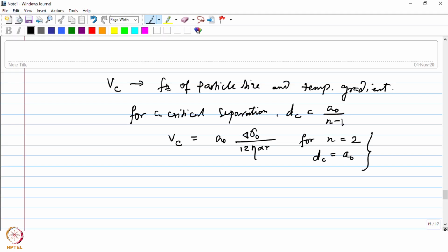Below the critical velocity, the particles are pushed by the solidification front, resulting in their segregation in the interdendritic regions on solidification. On the other hand, above the critical velocity, the front grows around the particles and engulfs them, leading to distribution in the grains.